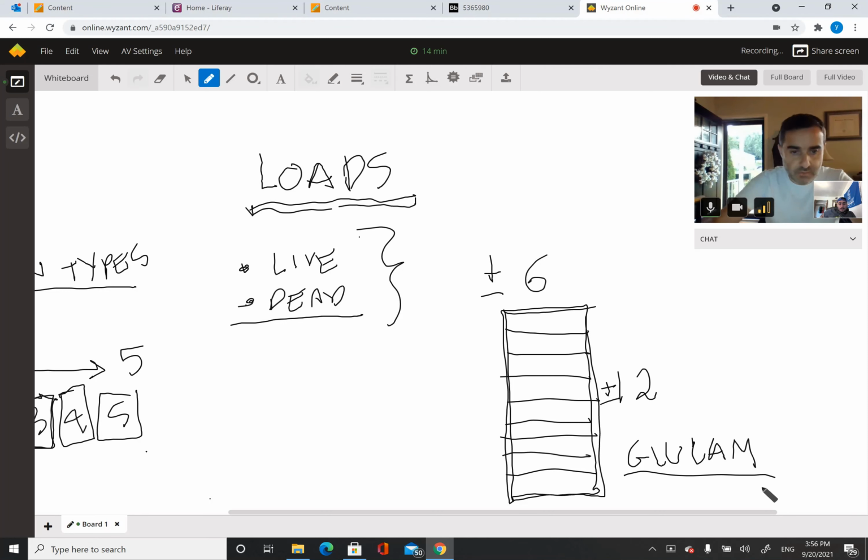But if you're going to do it right, that's how I would recommend it: you do an analysis of the type of foundations. Obviously in a hypothetical project where you don't have a lot of information on the site, you're going to start to make some recommendations. For example, if you're designing a tall 20-story building, you're not going to put a shallow foundation under it. You're probably going to go to a deep foundation.